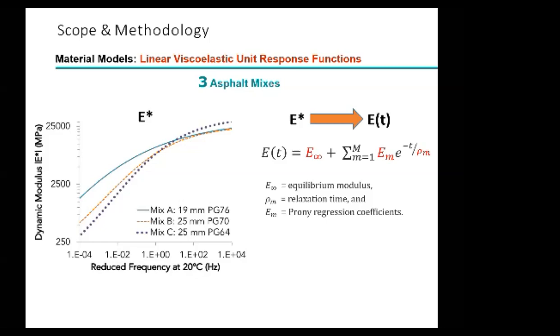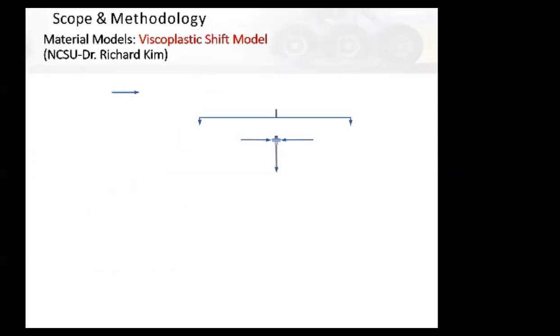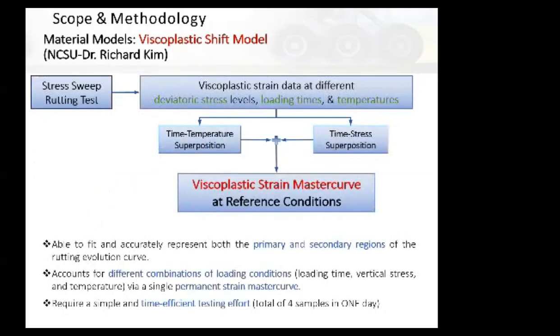Those are the actual dynamic modulus master curves. To ease the modeling and to input the material characterization in FlexPAVE, you had to convert it to relaxation modulus, E(t), and represent it in its Prony series format and input it to take care of linear viscoelasticity. Then that takes care of linear viscoelasticity.